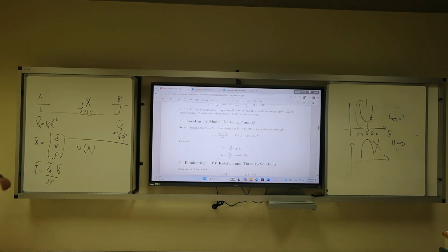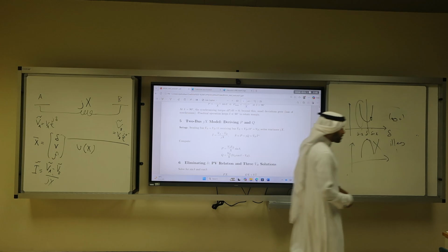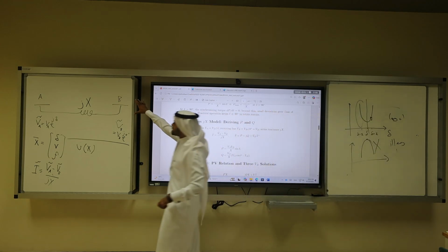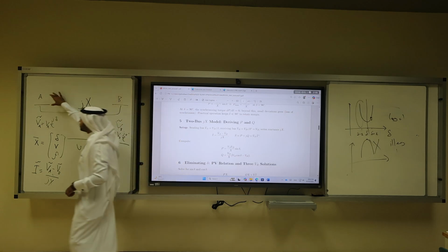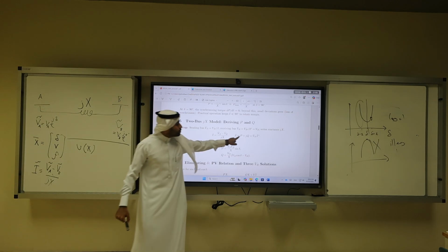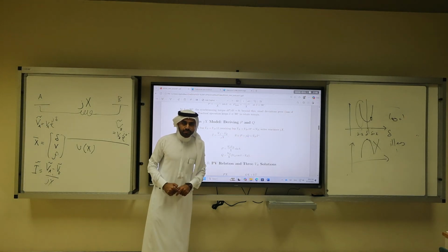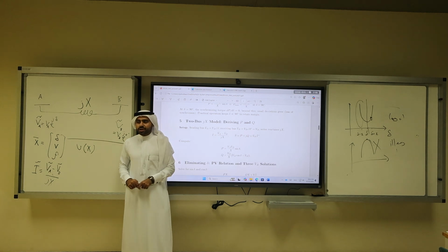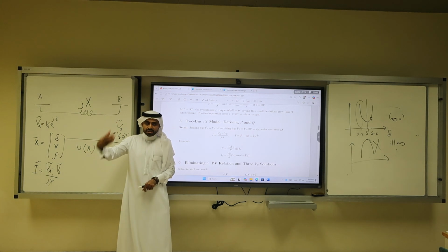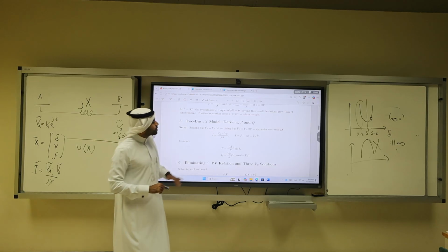That's very important. So here, what is the complex power? The complex power that goes to bus B, so this is the source and this is the load, is calculated using the equation VB times I star. What is star? Complex conjugate. I star is the conjugate. It means flip every j to minus j. j is the square root of minus 1. We will solve an example later about it.